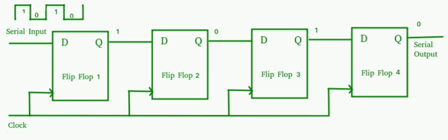Counter type ADC. The number of clock pulses required for n-bit conversion = 2^n − 1. Maximum conversion time = (2^n − 1) × Tclock. Counter type ADC is also known as ramp type ADC. In this ADC, the conversion time depends on the input analog voltage.